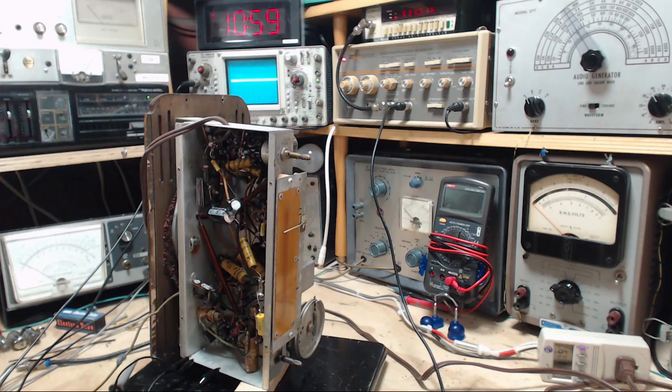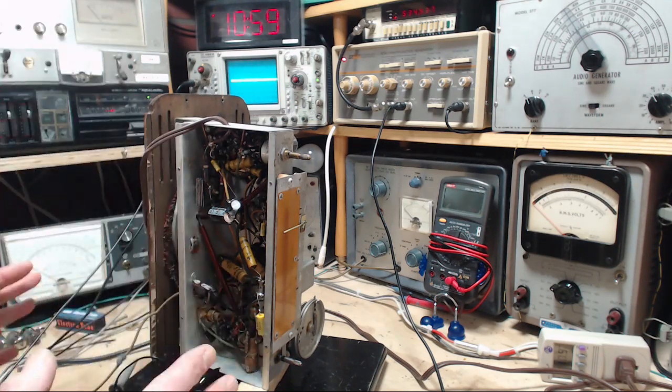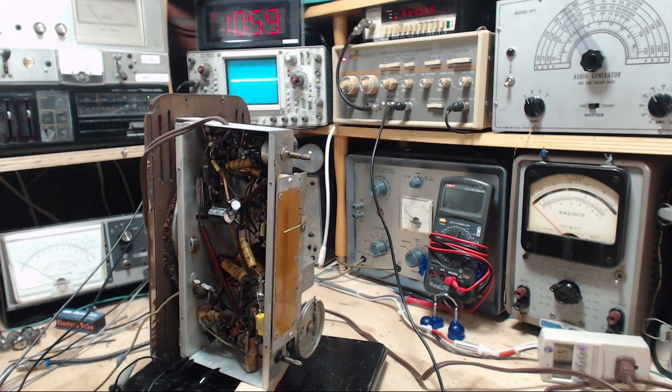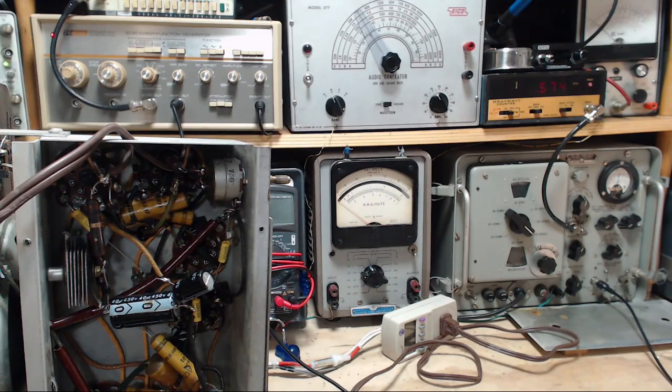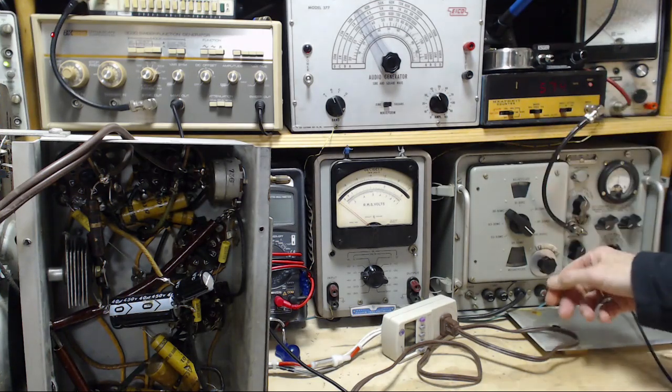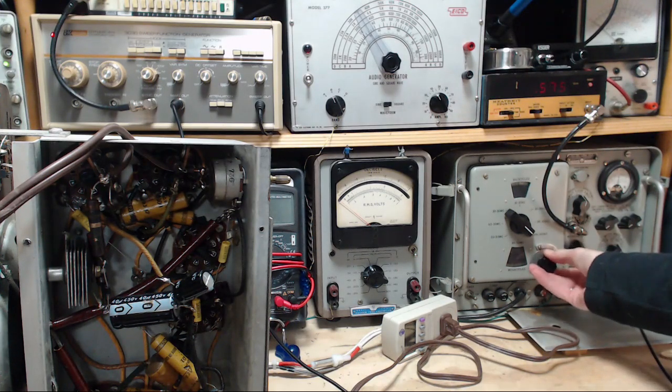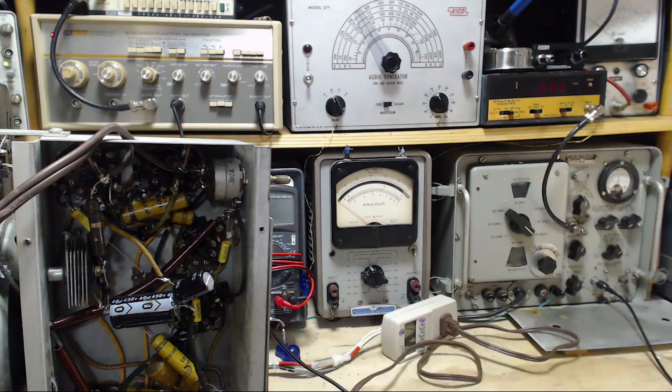Oh, that's a pretty ugly sound. It's possible we're tuned right on a noise signal. So what I should try doing now to determine if this is picking up 574 is fiddle around with the signal generator. 574. The answer is no. 600. So that tells me hooking up my scope is throwing the resonance of that first circuit off.